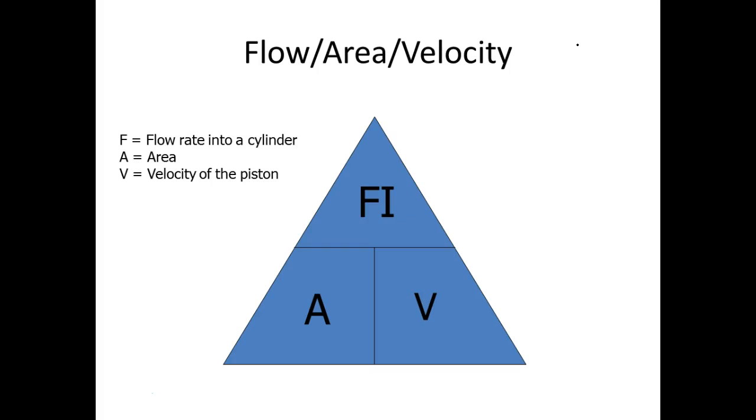When you start looking at pumps, they're rated at pressure, but they're also rated at flow. If you ever bought a compressor, cubic feet per minute. Cubic feet per minute. Well, that determines how fast things move. It doesn't determine how much force you can generate. Flow is the main determining factor of how fast things move. So where's force in there? Force is not even in there.